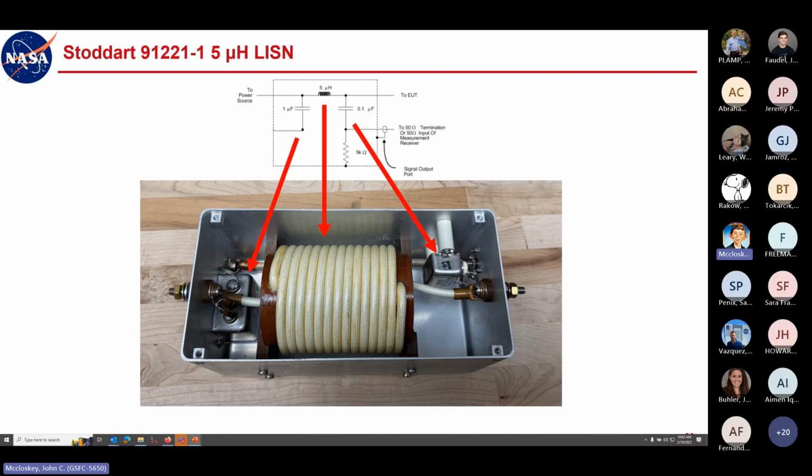So even microhenries of inductance to a distribution point is just not realistic for what we do. Now, if you think about the power in the building you're in, that wiring could be running tens to 100 meters from the service panel in the building to the section of the building where you are, where a bunch of outlets are ganged together. There could be a much more significant common source impedance there, because it's one set of wires, one running to